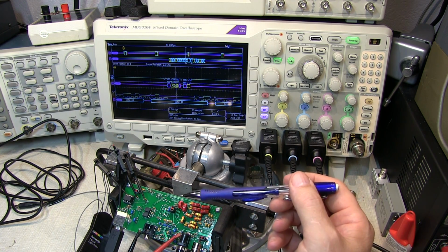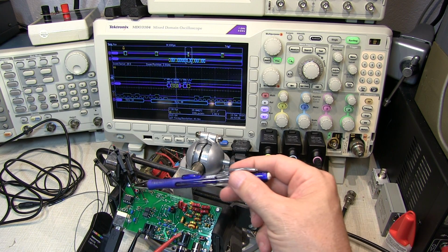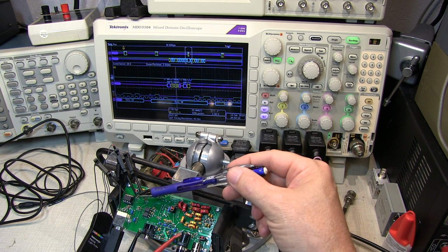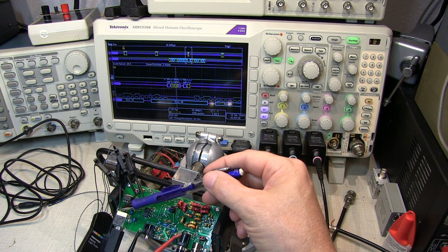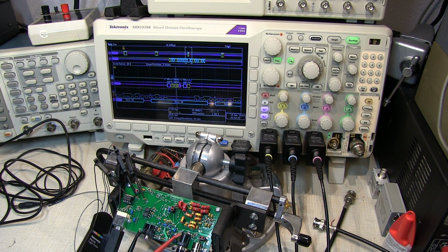And possibly later on when we do some of the measurements, we'll have the board flipped over so we can see that. Okay, so the first thing we've got instrumented here is I have some digital probes probing the I2C pins here and here, as well as the USB pins coming off of the USB connector here. And if you watch carefully on the scope, as I change the frequency that we want to program, we can see the data changing on the scope as I flip back and forth.